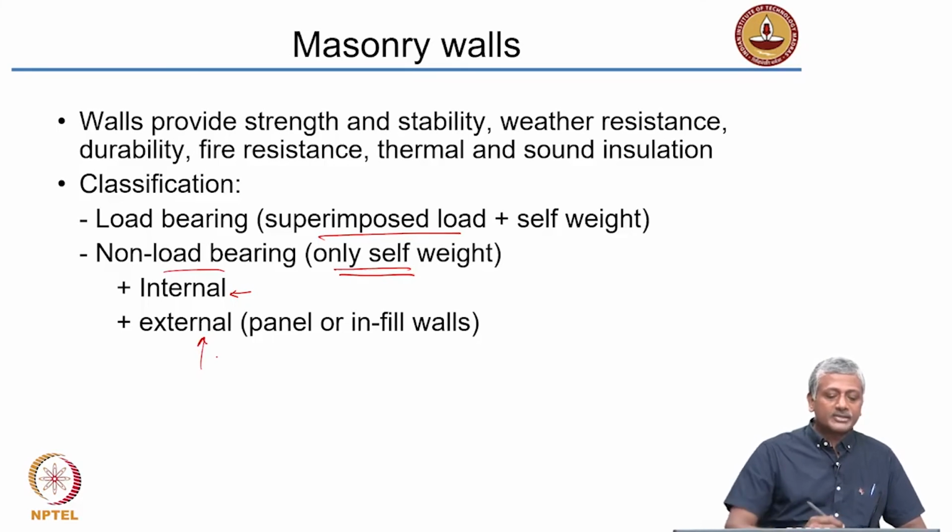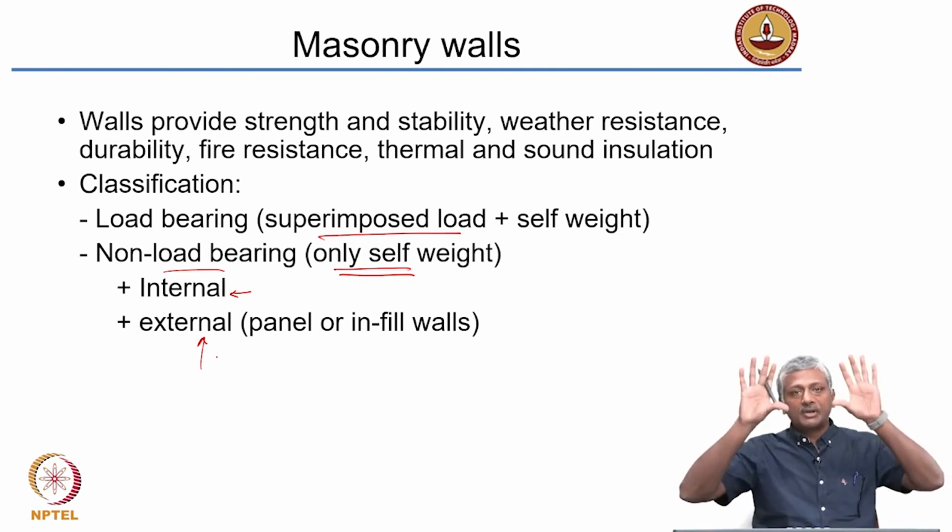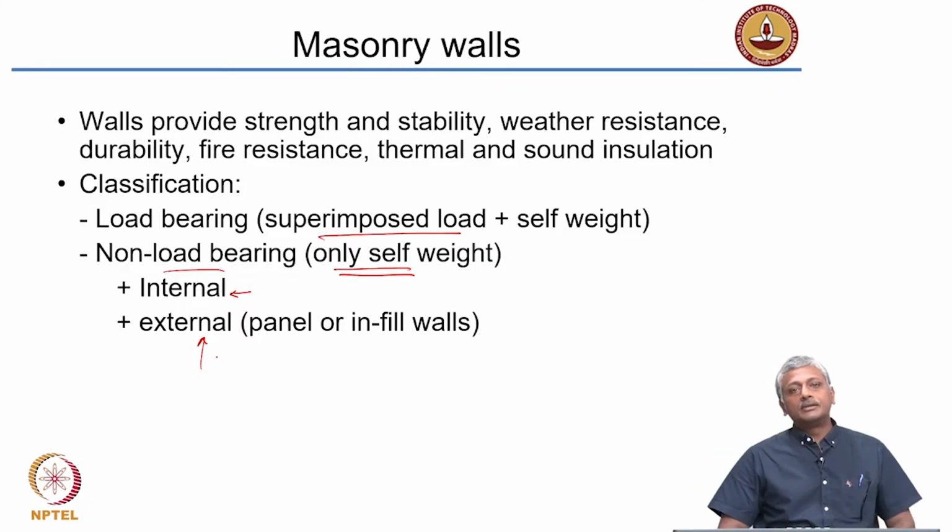The external walls, which are non-load bearing, are basically the panel walls or infill walls. As I said, in a reinforced concrete frame, you just fill up the location in between using a wall where you can actually have lightweight units also used. So that's called an infill wall.